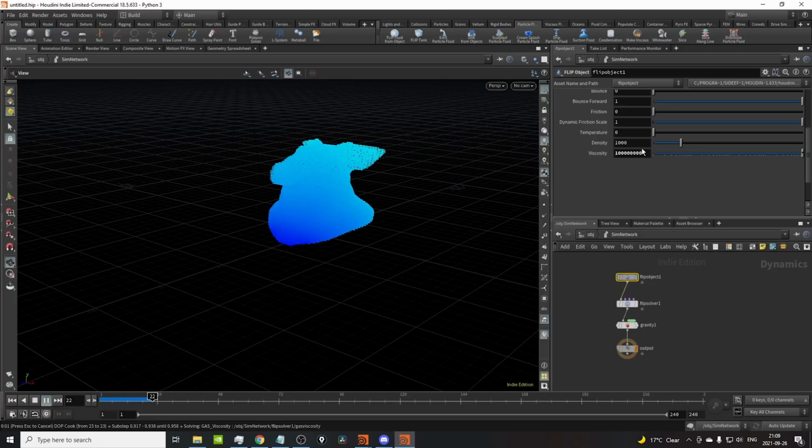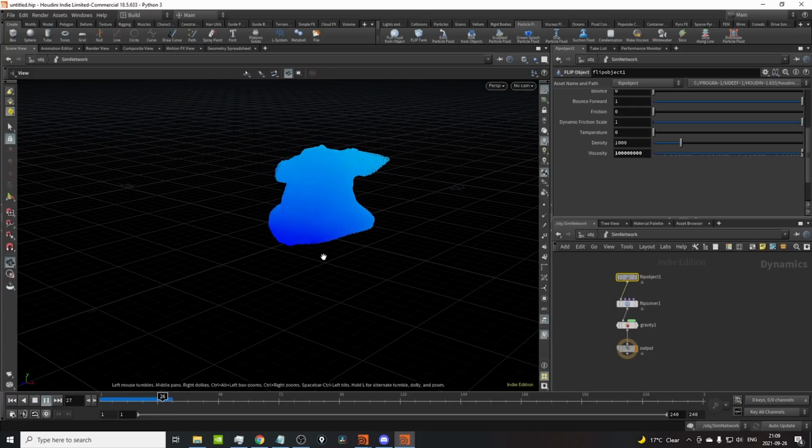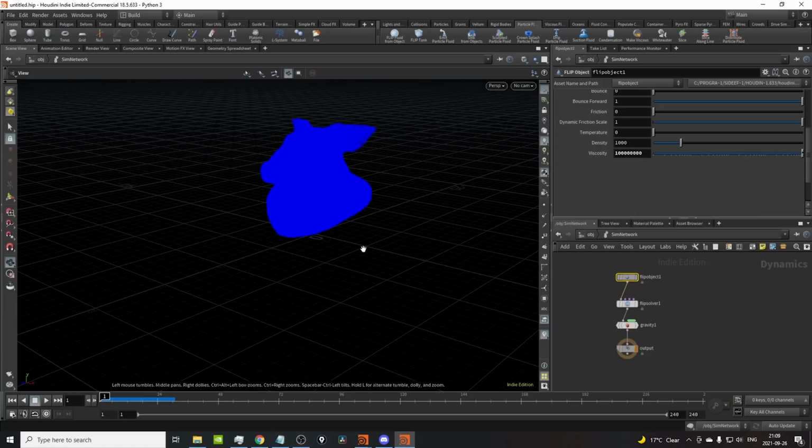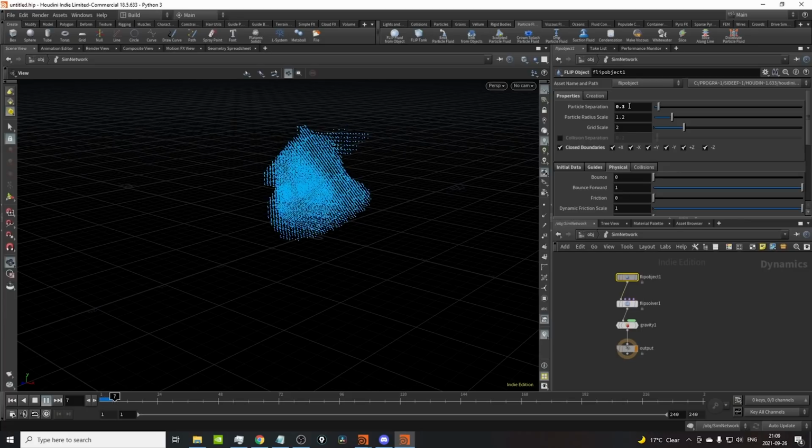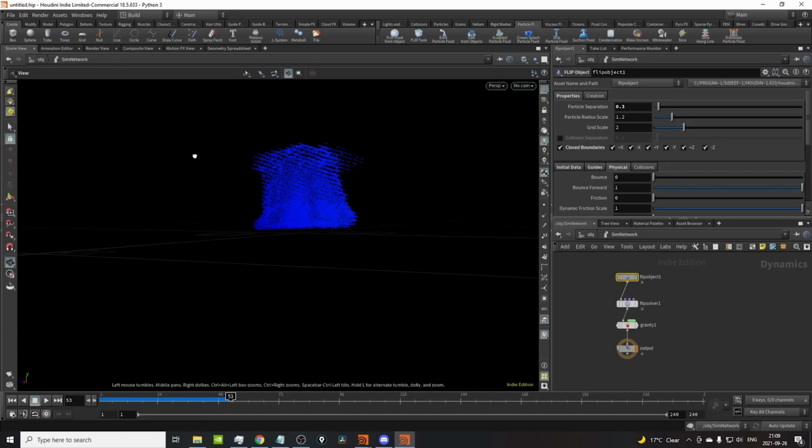The thing is, viscosity is also very slow to solve. As you can see, a lot of this time down here goes against gas viscosity solvers, right? So having viscosity turned on slows down your solver dramatically, but it solves it, right? And if we decrease the resolution on this a little bit, you know, we can see that good old pig is actually landing and holding its position.